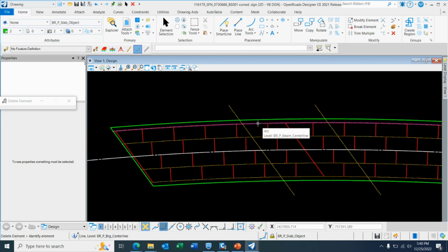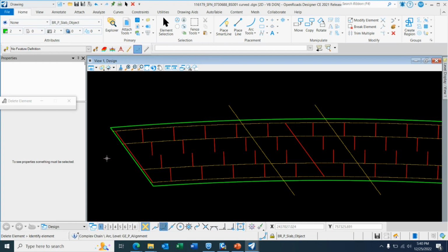And these two lines are splice locations. I intend to put a node at the intersection point on the beams so that I can start a different section in this negative moment region. So I'll just keep it for now, just for the purpose of providing a reference point. I don't need this center line of construction, so I will delete this too. But I will just keep it for now because I don't have any beam line there.